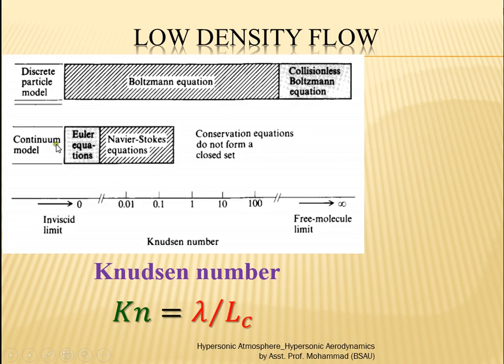So we have a continuum regime from here to here, and it's not exactly Knudsen number equal to 1, but it's very near to 1, so we can take it as somewhat similar to 1. We can use the continuum model. But the moment it goes beyond 1, the no slip condition is not valid, and the slip condition regime is applicable there. That is applicable throughout up to infinity.